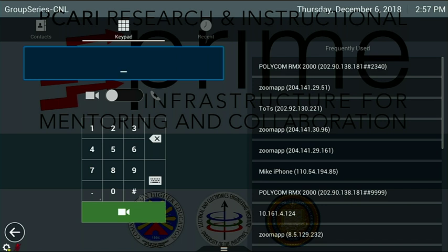Actually, there's only one way of telling if this is stable in the time domain, and that is by doing the simulation in the time domain. There actually is no other test for stability than simulating in the time domain. So let's do it. Let's take the inverting input, connect it to the output, unground that. Now it's a voltage follower. I will comment out the frequency domain, run it in the time domain, and there's the output, there's the input. It's perfectly stable. It has no phase margin.